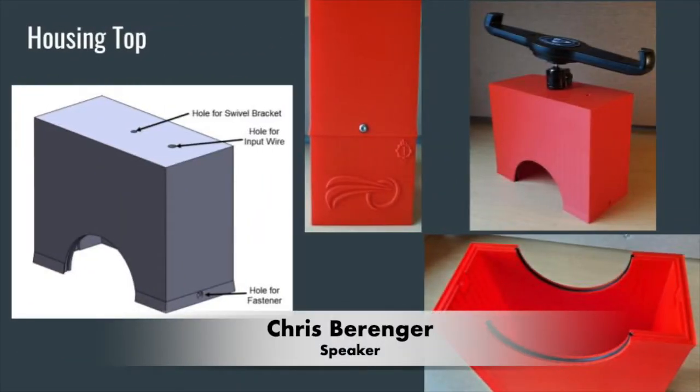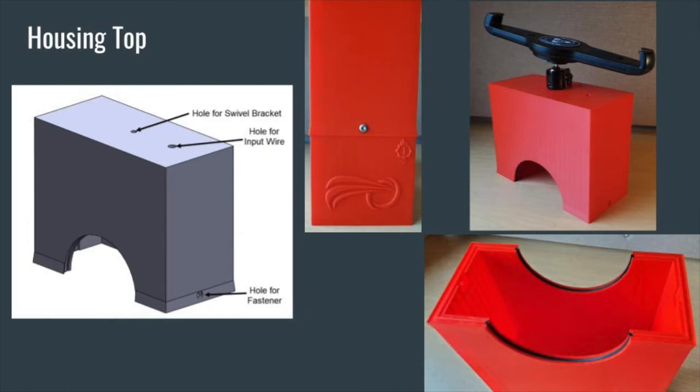The top of the housing is designed to accommodate the long sensor clamp arms. This portion of the housing is placed on top of the pipe and clamp arms. The provided security fasteners will bolt and secure the top of the housing to the bottom. This will be a pressure fit, as both the top and the bottom have a 3mm gasket designed to compress when installed. In order to aid in waterproofing, the top of the housing has a small lip that runs along the base of this part. This lip is intended to stop any liquids from landing on the main gasket.